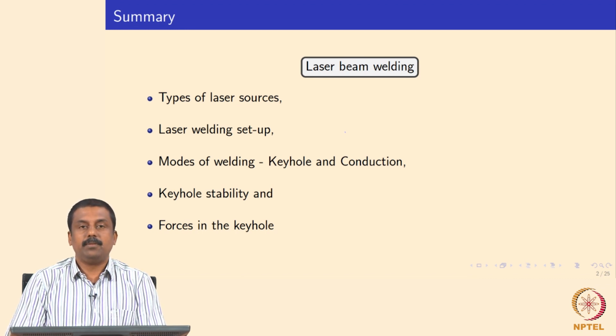In the conventional process we use a constant current. For example, the amplitude of current is constant throughout the welding process. There are some disadvantages in terms of heat input, the amount of heat you put into the workpiece, as well as the transfer characteristic. So what do we mean by transfer characteristic? It is how you transfer the molten droplets from the electrode to the workpiece.